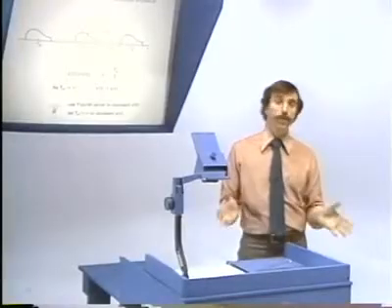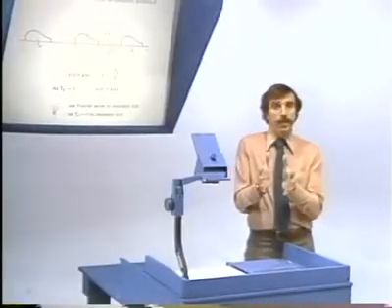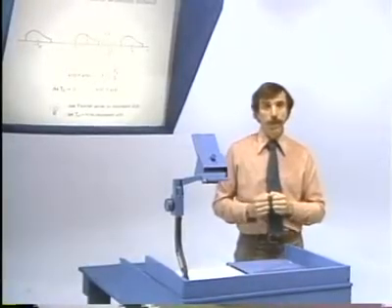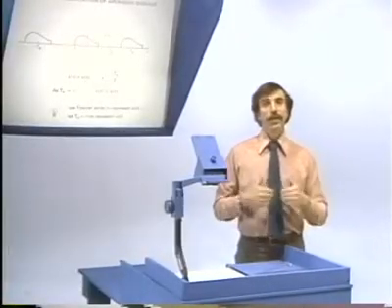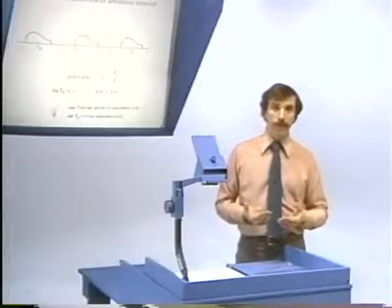As the period goes to infinity, that periodic signal becomes the original aperiodic one that we had before, and the Fourier series representation then becomes what we'll refer to as the Fourier transform.